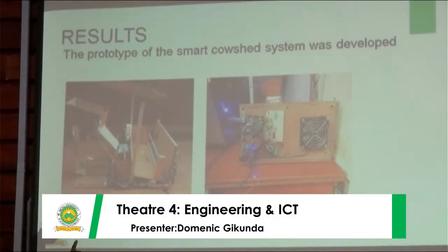When it detects, it's controlled by the Arduino and controls the opening of the servo motors. Inside here we have vibration motors, which cause vibration and allow flow of the feed to the compartment. And as you can see, there is a fan for the temperature control. This was the control part of the system, which involves the use of Arduino and the sensors.